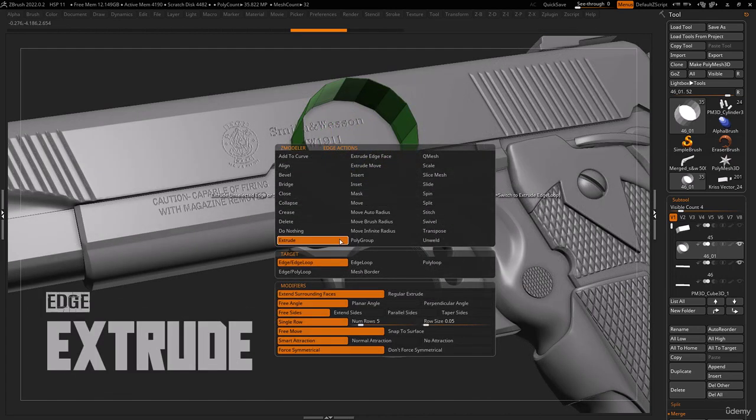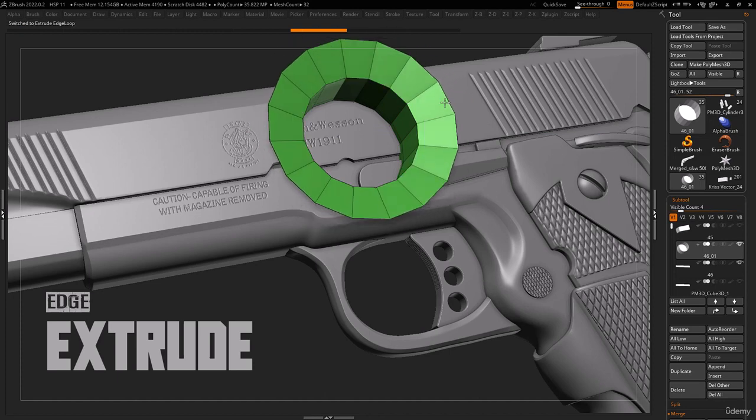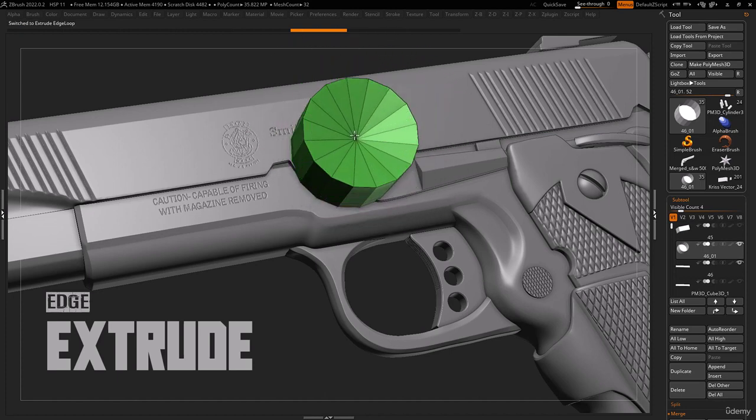With the extrude edge action selected, you can click and drag to extrude and connect edges. Extra features are highlighted in small text under your cursor. While extruding an edge, press the Alt key to extrude all connected edges. Your points will connect and merge with nearby points.